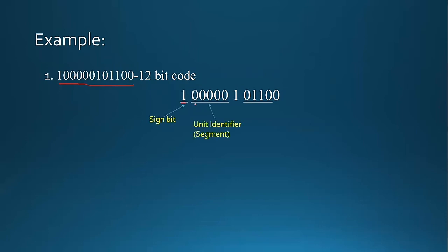Based on the steps, we must have the trailing zeros followed by 1, which is our indicator between the segment identifier and the quantization interval. We must always assume that there is a 1. Then we have the 4 bits for our quantization interval. Then the rest of the bits would be the truncated bits.